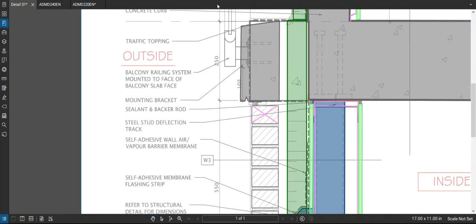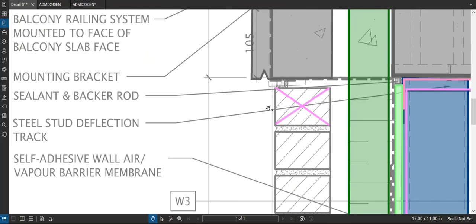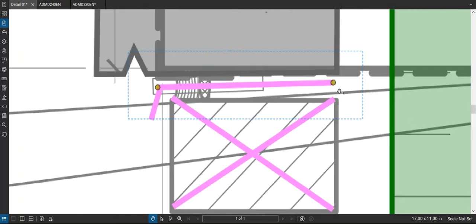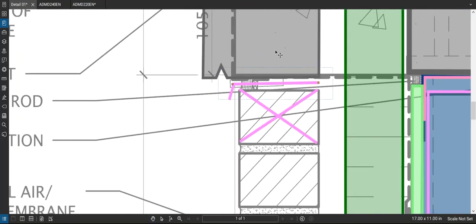I wouldn't say it's absolutely necessary in this particular situation, but if you read some literature from brick associations, they would recommend a flashing put between the concrete and the brick, and that's mainly because of efflorescence. So the concrete itself could have some salts in it that could migrate into the brick, and then you start to get that efflorescence on the front of the brick. It doesn't always happen, but the potential's there.